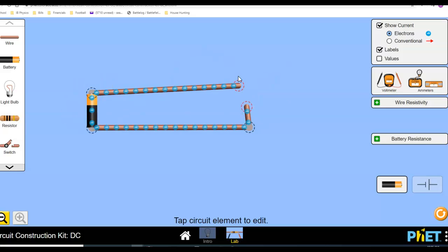Okay, there's nothing hooked up to the circuit that's using its energy. There's no light bulb or cell phone charger or anything like that. And so if we just take wires and attach them together with nothing using up that energy, it has to be used up inside the battery itself. Which is bad for the battery and also can be dangerous, because then the battery can heat up and possibly explode. And that's not good. So you want to avoid short circuits.